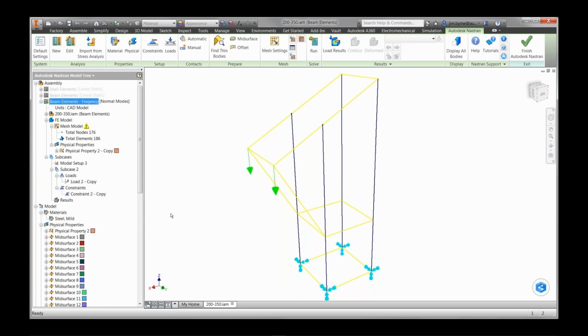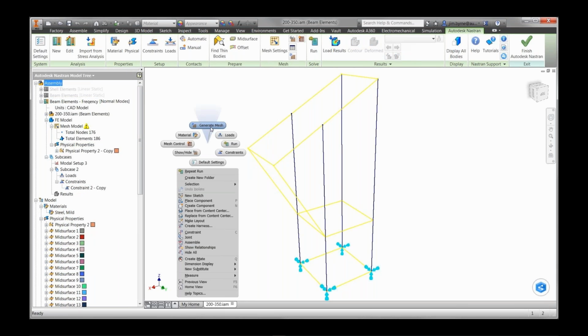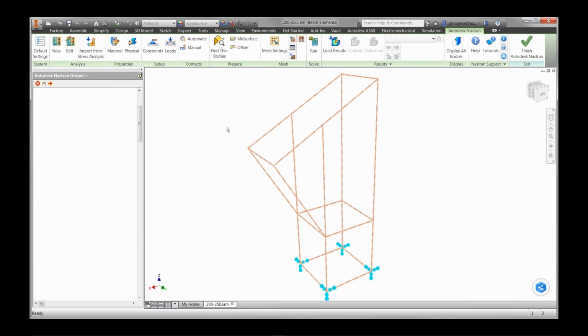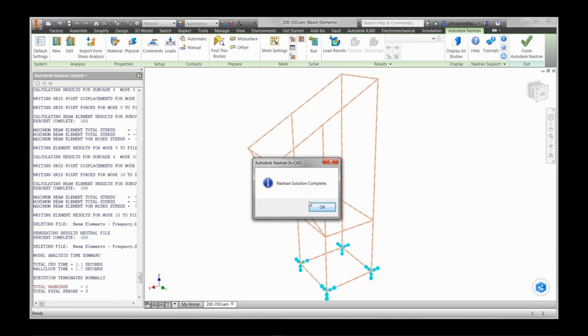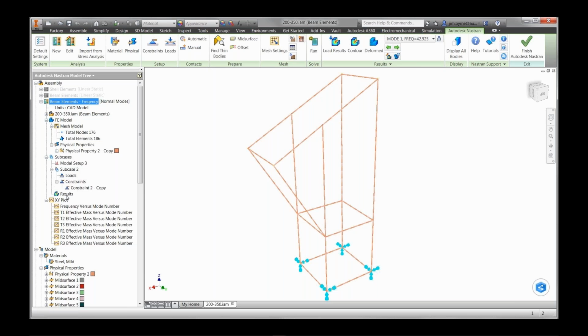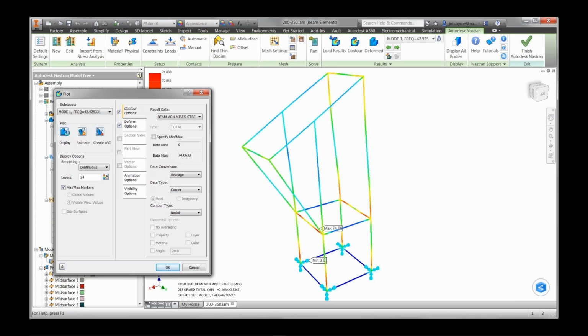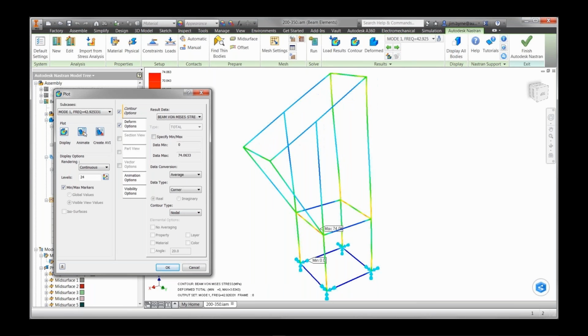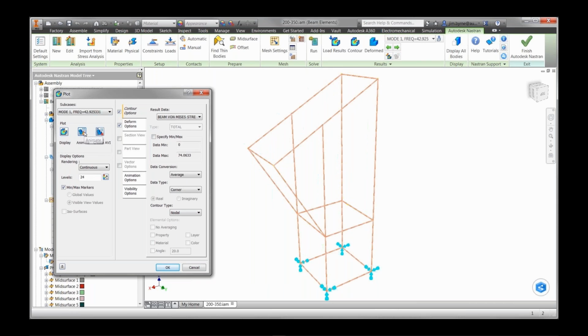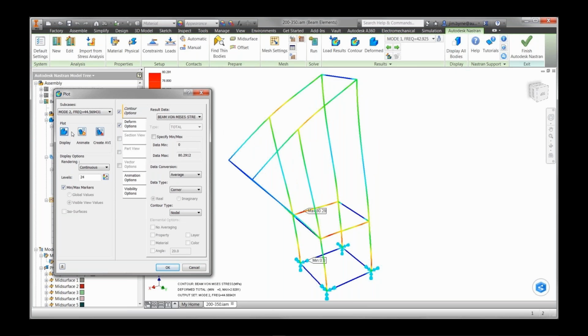So this gives me the chance to show whether we can do a modal analysis or not. Now I am creating all three different types of scenarios in the same project actually, just doing a copy paste of that one. So with this I can find out the different frequencies and which direction those frequencies are in. This one is left to right. And two of these frequencies are very close to each other. You can see that, and now I'm going to run the animation for it.